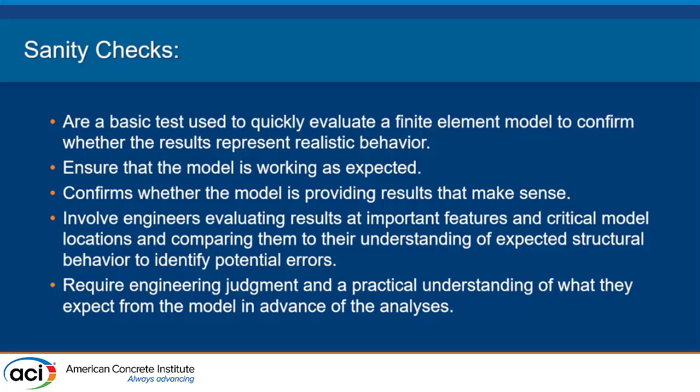And then as a sort of brief introduction to sanity checks, it's really a basic test used to quickly evaluate a finite element model to confirm whether the results represent realistic behavior. It ensures that the model is working as expected. It confirms whether the model is providing results that make sense or are sane. It involves engineers evaluating the results at important features of the model at critical locations and comparing their understanding of the expected structural behavior to what they're getting.